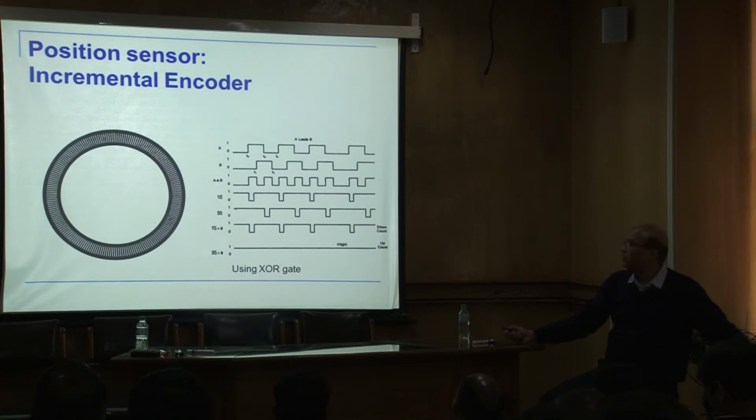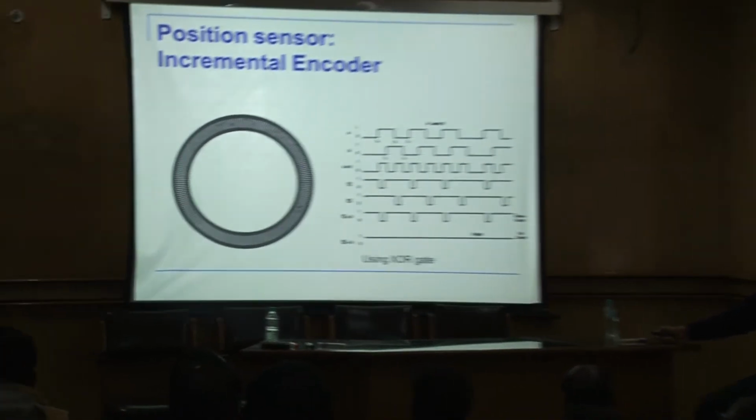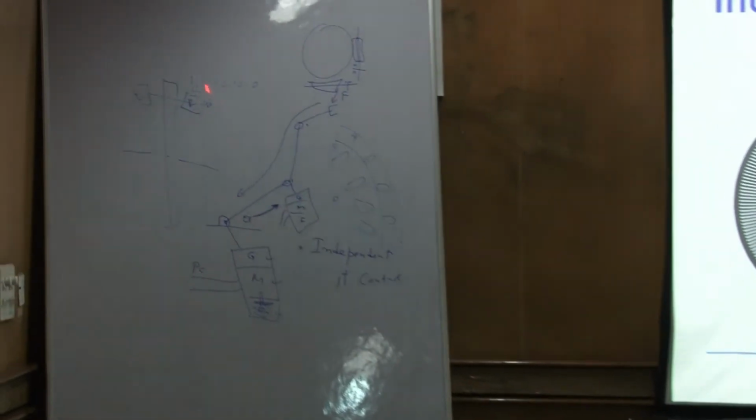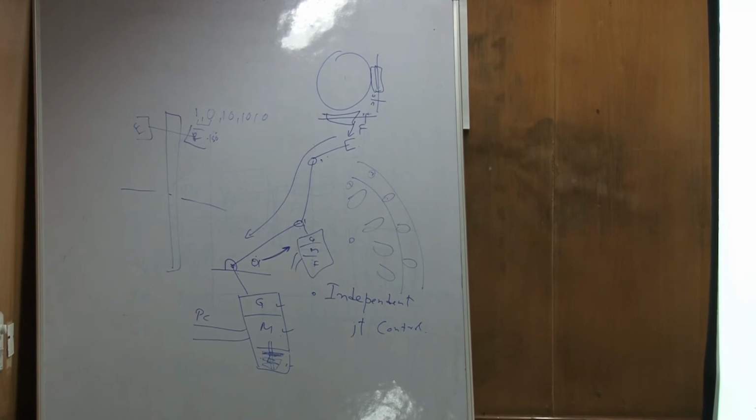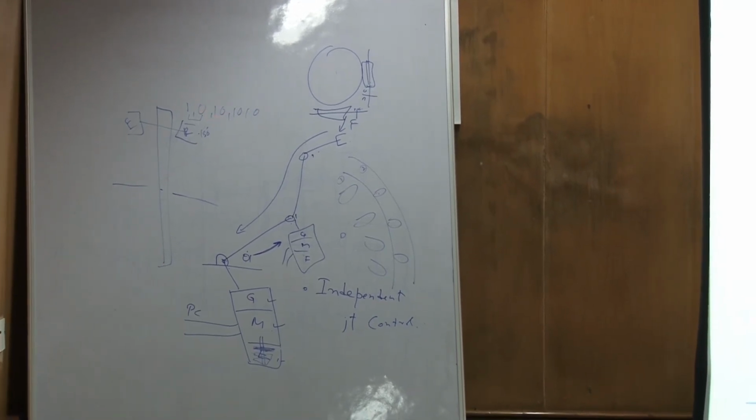Okay. Now, in terms of the feedback loop, we require the position, we require velocity, and we require acceleration, because the controller needs all those things. Now this is giving me the position, because I know the distance between both of them. How can I get the velocity from here? So we know this is the distance. So if I know how much time it took to go from here to here, I can do this by a dt. So I can get incremental velocity, right? So this is not only giving me position, it's also giving me velocity.